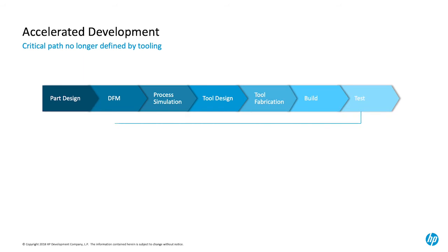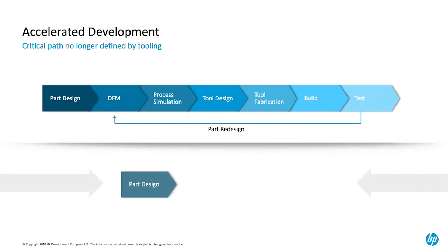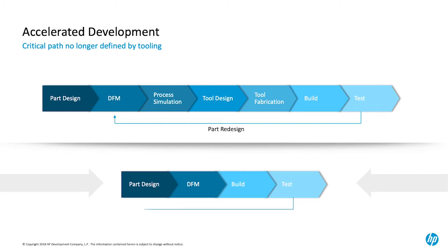When you're first getting into additive manufacturing, essentially what you're getting rid of is the tooling cost, the tool wait time, and minimum order quantity, with the majority of the technologies that you use today. With 3D printing, you are able to cut that part out and design, print, post-process, and then test the parts. In the normal process of part design in new product development, if you have changes to the part, that essentially means new molds being made. That means new costs and new wait time, which add on to the product development process.